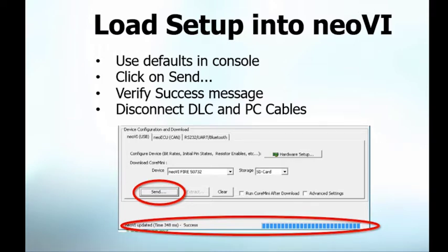If we didn't have that option and you had some bad script running that was in some sort of infinite loop or something, you would have no way to stop it without the USB connection. Now, you can unplug USB, power cycle it, the Core Mini will run, and then you can re-plug back in USB and connect to it. And that's another big perk of our tools. I'm not aware of many data loggers that do this, and I know our biggest competitor in this area does not do this, where you can have a data logger in your car running, recording data. You can also connect VehicleSpy to it at the same time. So you can still do online analysis with your data logger while it's logging data.